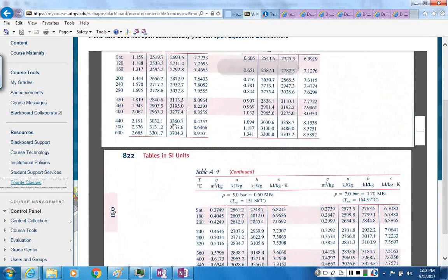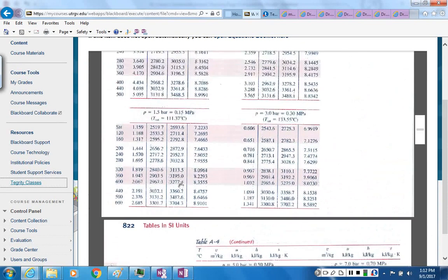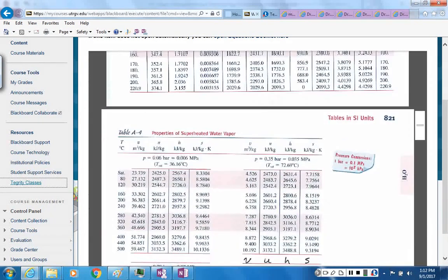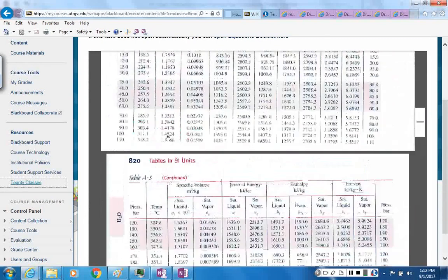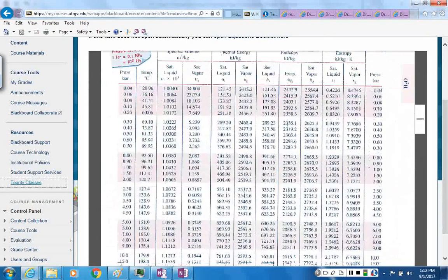And this looks like not going to be in the saturation table, so let's go to the pressure tables, and we're at 0.4 bar, which is here, and we're going to compare the entropy, and it looks like our entropy is lower than the saturation value, so we're going to be in the saturated tables. If this entropy was higher than 7.67, then we would be superheated.